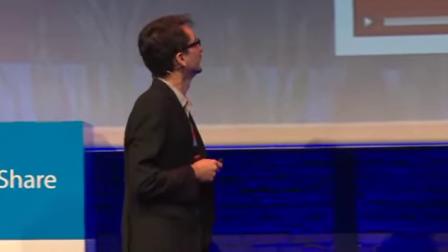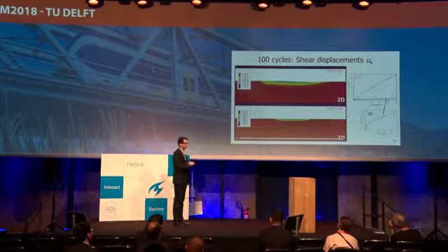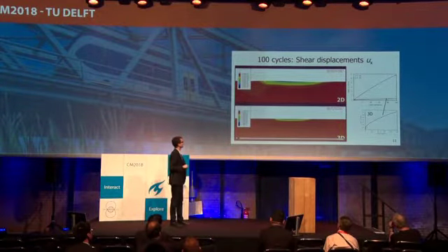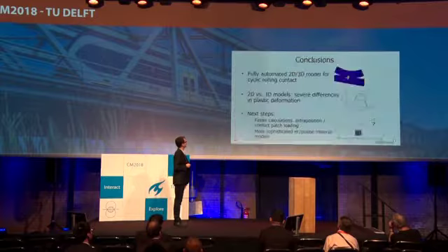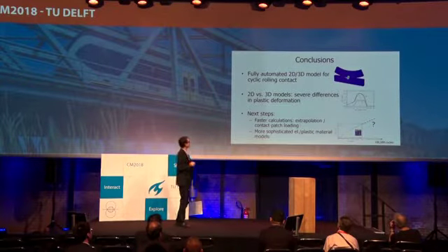I didn't mention this in the beginning, but of course, in the rail, or in this test rig, we have a very long rolling length. But in the model, to keep it efficient, we should take a rolling length which is as small as possible, because double the rolling length is double the calculation times. Yes, that was what I wanted to say, basically.